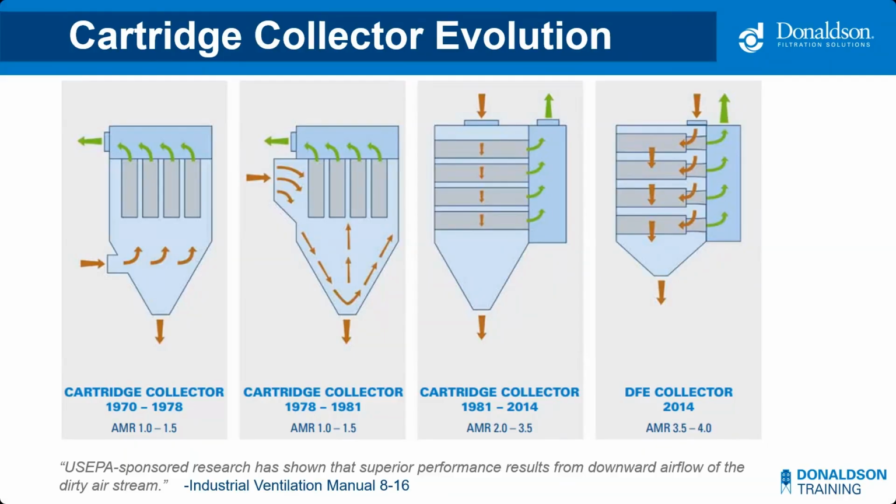And that worked a little bit better, but it created a different set of abrasions. So we had abrasion on the left side there. Still had some can velocity concerns, but it did reduce that as well. I should point out that there are still some dust collector manufacturers that use this style of cartridge where the filters are vertical like a bag house. And we actually have a few specialized cartridge collectors of our own that are vertical filters, but they're used for very specific situations, which I'll show you an example in a few moments.